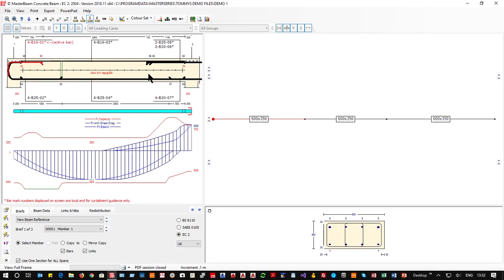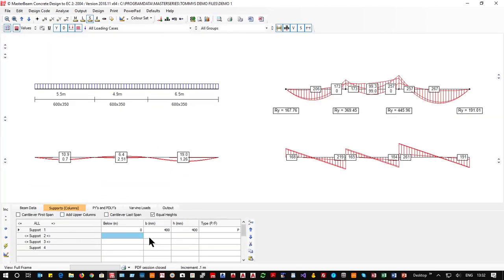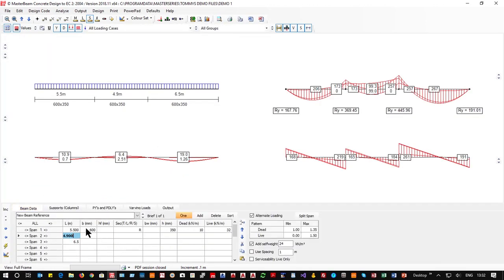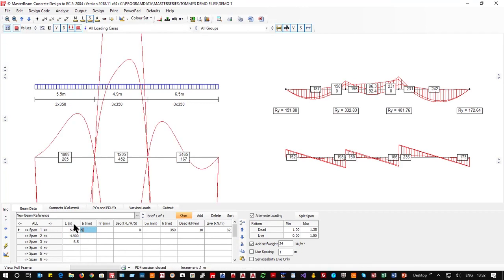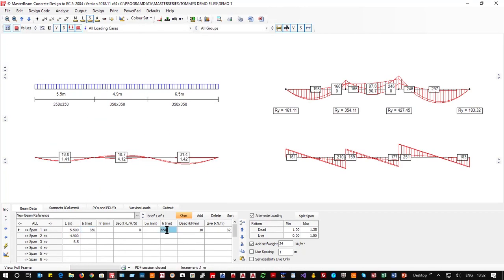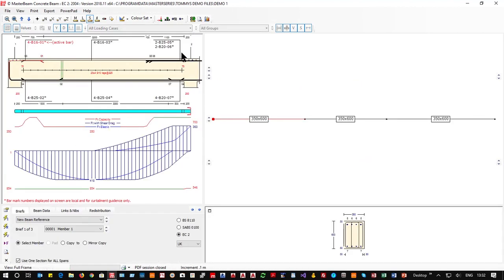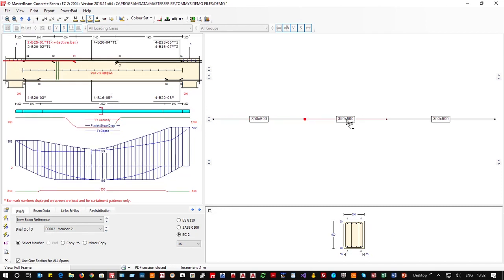And I think we're into very heavy steel. For my loading, I probably need it. Actually, I got my directions the wrong way round. So, out of this, back to here, and it is 350 wide, 600 deep, and a little shortcut to design is in here. And we should now find, if we do an auto design, that we've got a more sensible 225s and 220s with 416s, 2s on these, and then we have the same.